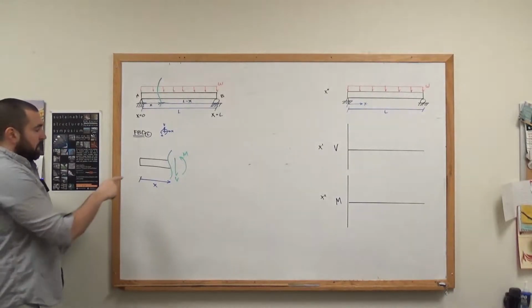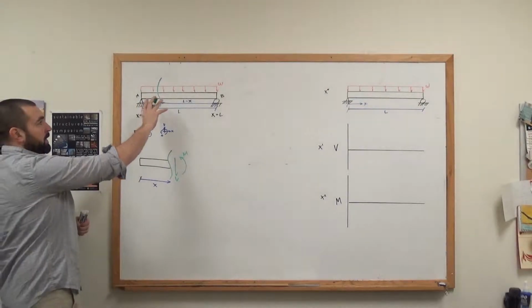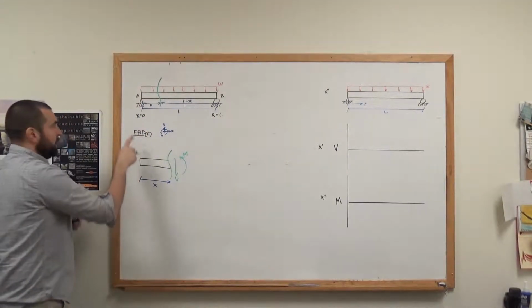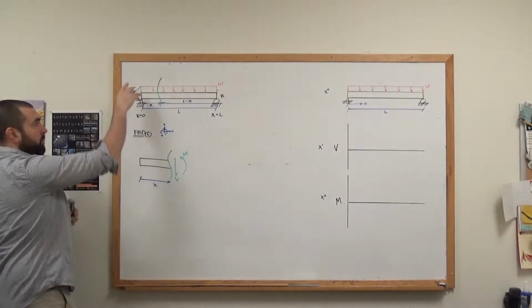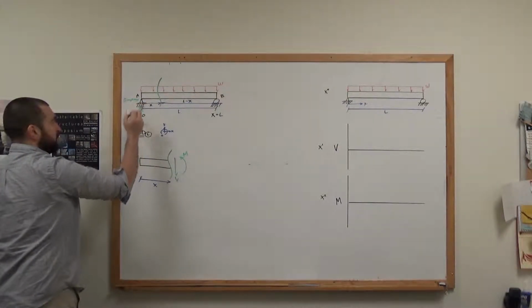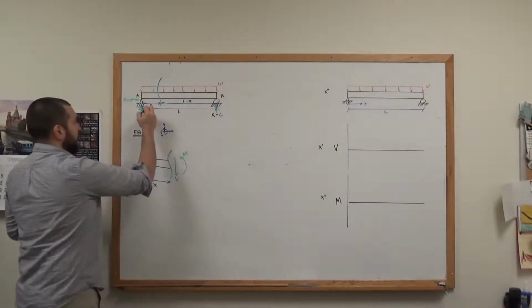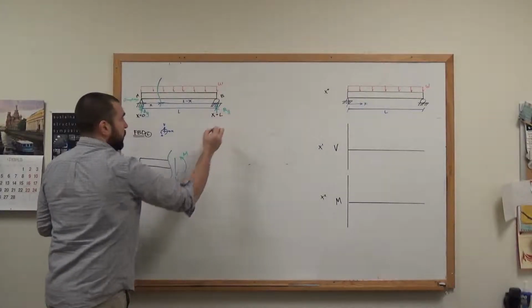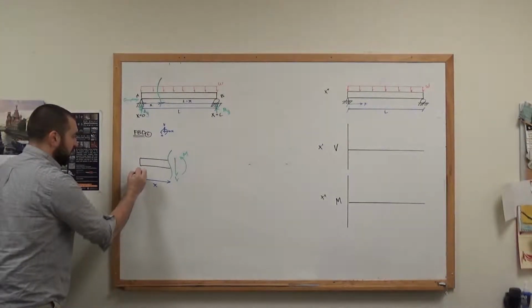And I need to have my support reaction. There's no way to get around it. I can't choose everything to the right of the section cut and avoid it because there's a roller over there as well. Now, the horizontal support reaction we know is going to be 0. There's no horizontally applied loads. The vertical reaction we'll talk about in a second for either of these. So AY and BY, the way that I would solve for those, and I'll need AY over here,